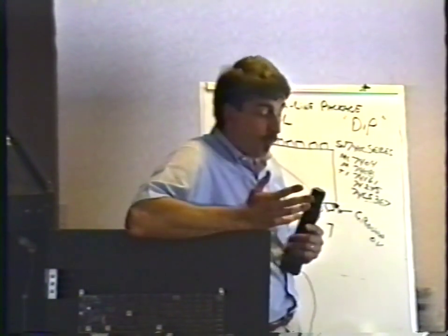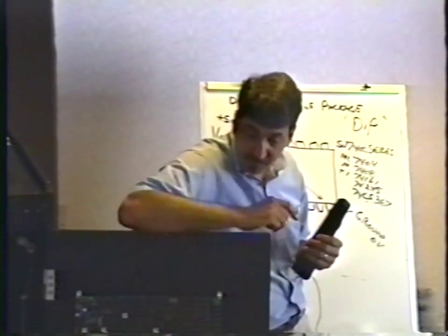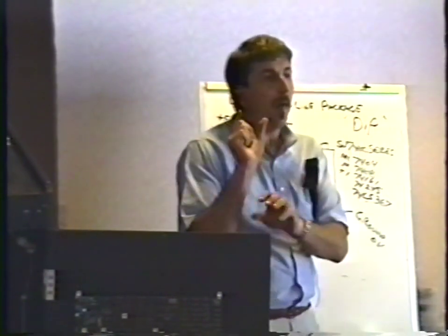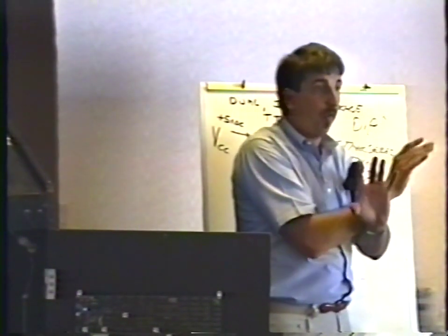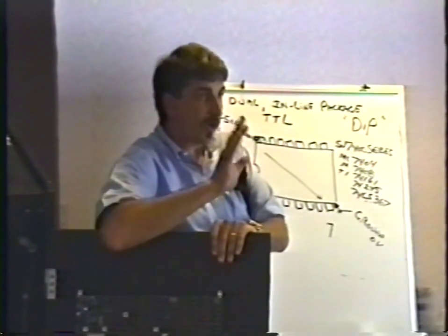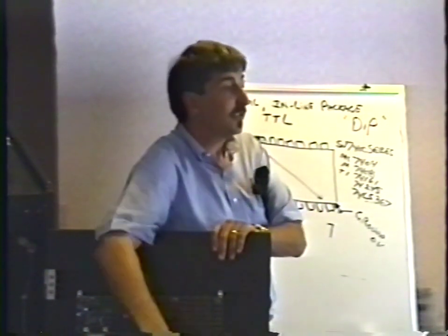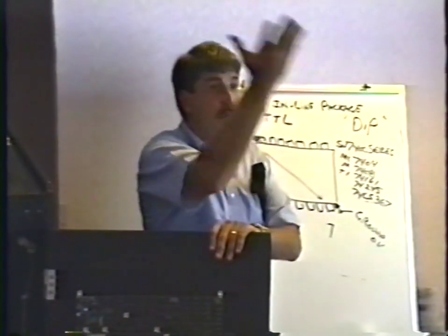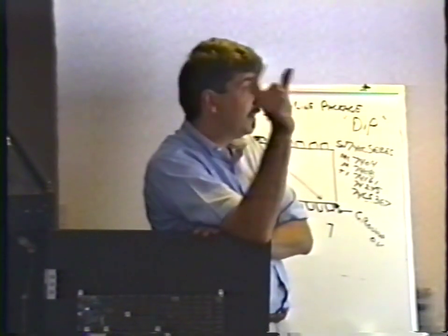So I took the bad boards and I drove 20 miles over to a location where we had another Outrun, and I sat down behind the Outrun, and one at a time I took the integrated circuits from the bad board and swapped them with the good working board. You should always do this. Try the suspected bad parts in your good working test bed. The reason you do this is that you may have more than one bad integrated circuit on your bad board. This way, when you move a chip over, you can tell: oh, I moved this chip over, now the problem's in my working game. Obviously, that chip that I moved over is bad.